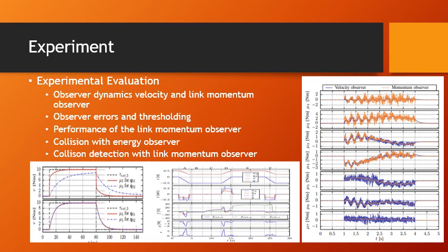In the collision detection zone, as you can see, there are four phases. In phase A, the external force is recognized by the detection scheme with minimal delay. In B, no external force is applied and the robot is at rest. In C, we see the detection is not possible, and in D, the robot is moving again, which leads to an increase in sensitivity and in the monitoring signal.